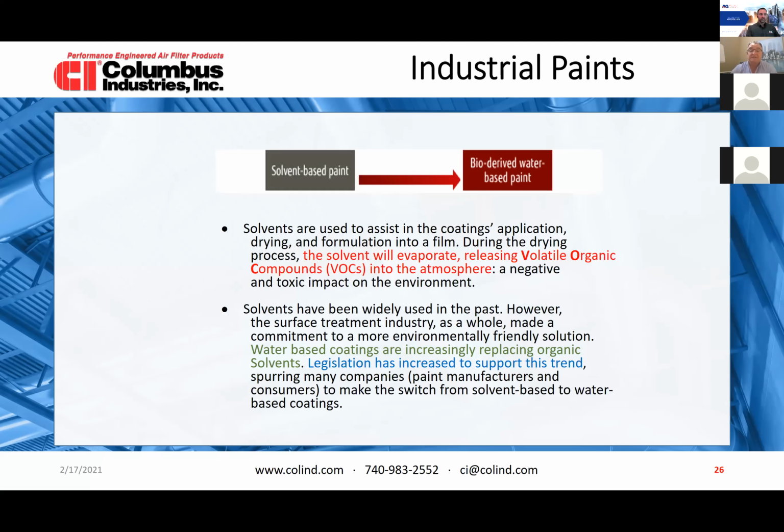Treating VOCs costs a lot of energy, a lot of money, because you need to take those abatement systems to very high temperatures. So again, it's a commitment, and everybody is on the same page as far as doing that. The end users, but also a lot of work has been done by the paint manufacturers in developing these new paints that are less and less solvent based, going more towards a bio-derived water-based paint.